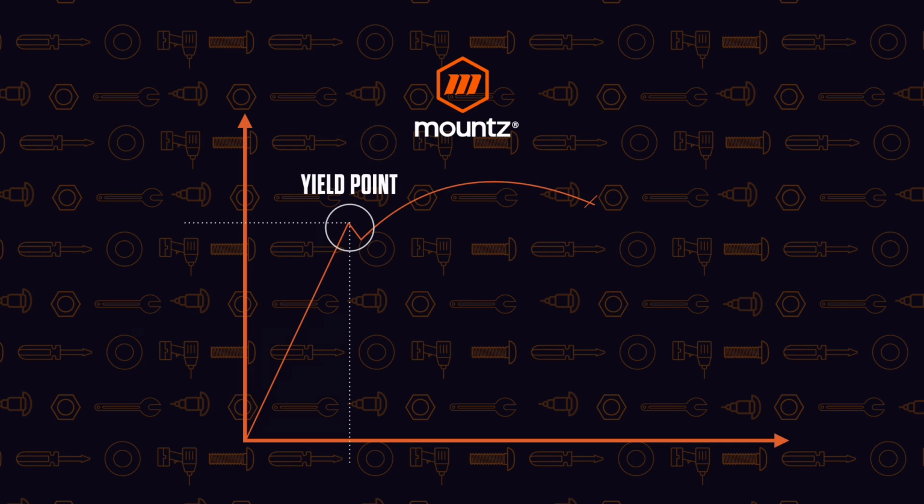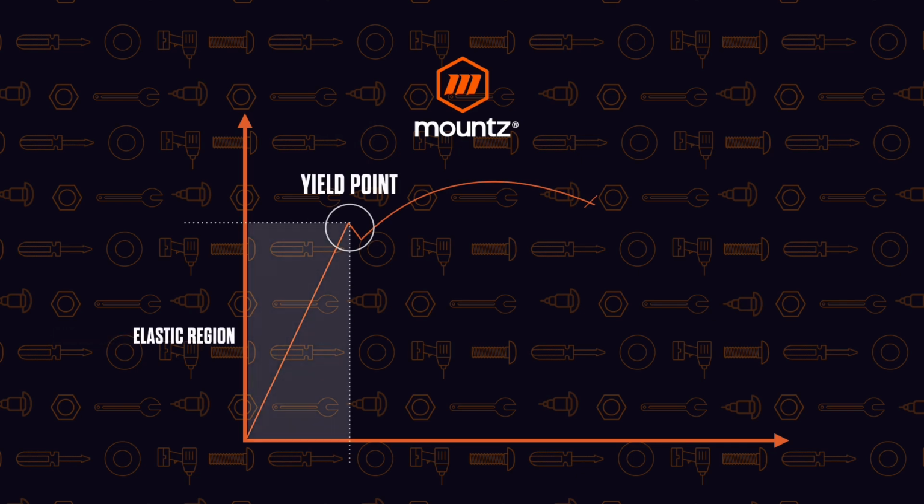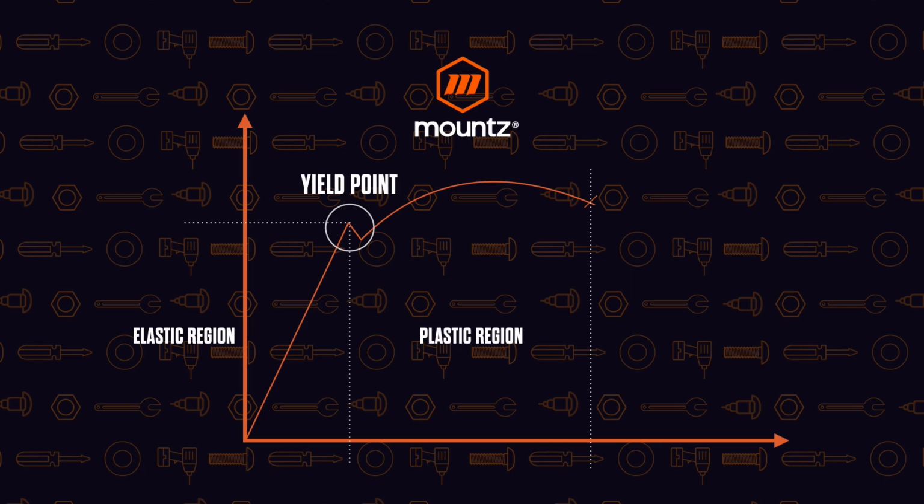Once we hit that yield point, that fastener is susceptible to failure with any type of shock or vibration that will cause it to break. As long as we stay below that yield point, we stay within its elastic region, meaning that it will return to its original shape.